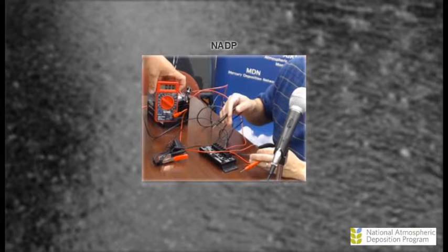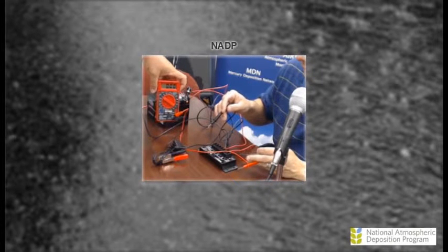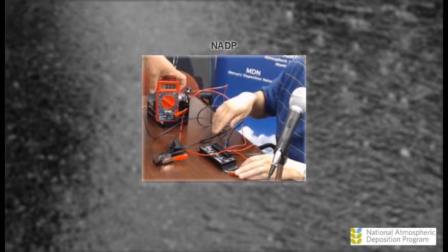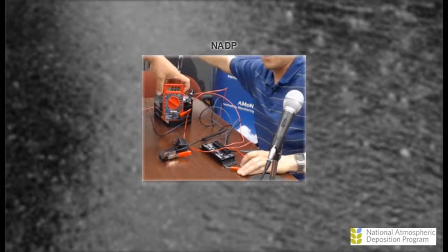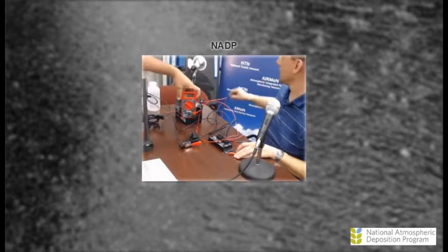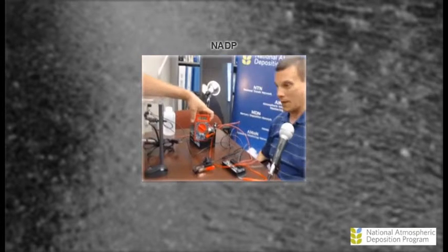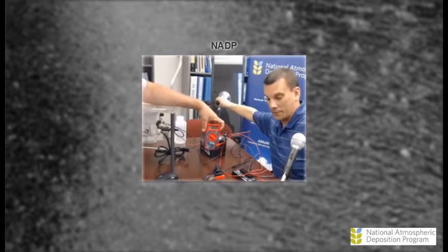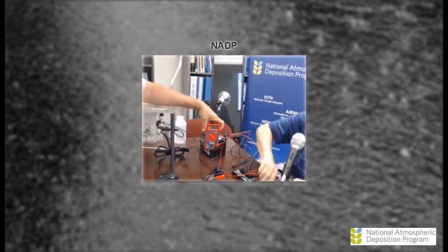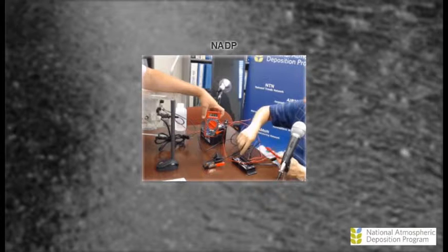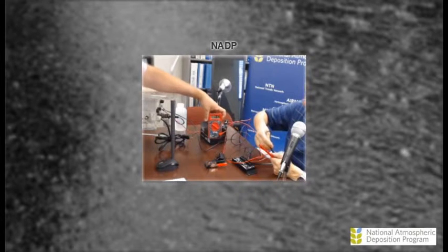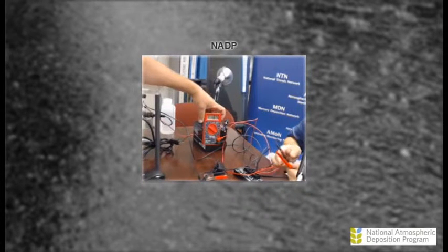The next check we're going to do is checking the regulation of the regulator. We're going to bring the sun out, turn on our sunbeam, because we don't get enough power here. Actually, we could show that. We'll start with a cloudy day. And the nice thing about DC is if you happen to hook up reverse, it just shows the negative. So we can see the meter. I actually have those in reverse. No harm done.